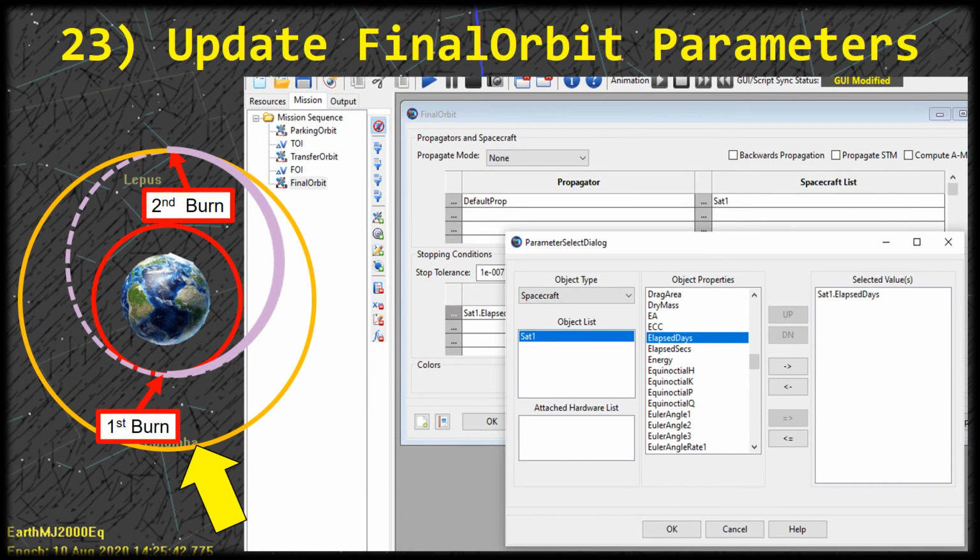All right, let's go ahead and update the final orbit parameters. So double click on the final orbit in the mission sequence on the left, and you'll see the parameter window pop up. Now we're going to change the stopping condition by clicking the 3 buttons here on the left. I'm just going to go ahead and change it to be elapsed days, just because it's going to be pretty easy to just make it rotate for, I don't know, half a day or a day, just to get it to go around its orbit at least once so that we can see it. Doesn't really matter where it ends up. So go ahead and find in the list elapsed days and click the right arrow so that it becomes the selected value and click OK.